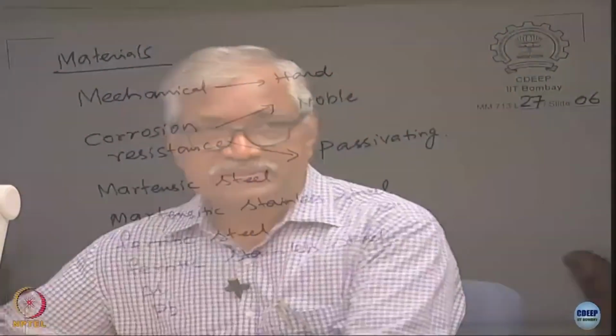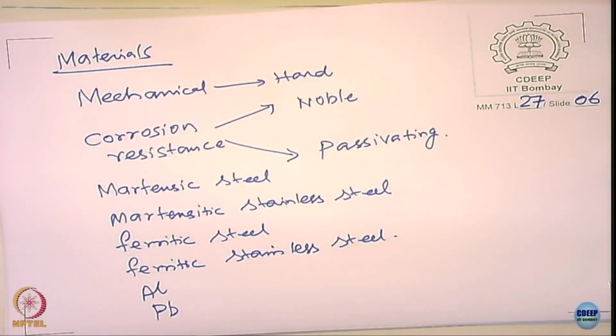So it is not possible to extrapolate from given velocities to higher ones, because at higher velocities the mechanism of damage may be different. It is more mechanical damage dominated than corrosion dominated. At low velocities, what is the dominating mechanism? Low velocities is corrosion. At higher velocities, the dominating mechanism will be the mechanical factor. So it is not possible to just make extrapolations the way you want.